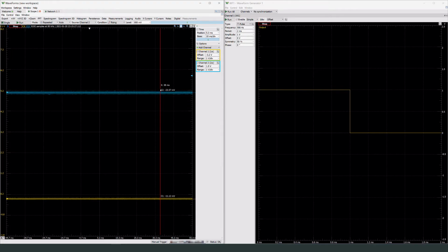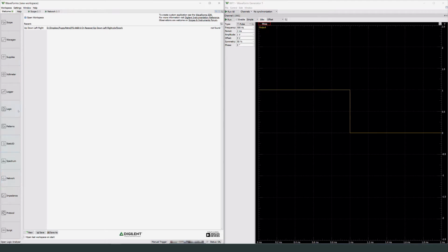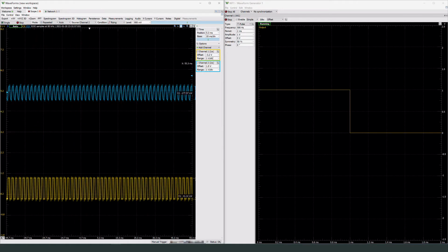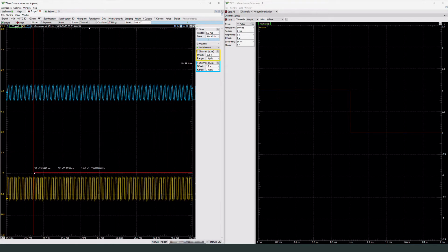But anything that we're dealing with right here, this is just great because it's got an entire electronics lab in one, where we have all these tools that we can use. And so right now we're going to use the oscilloscope and the waveform generator that we have plugged up. The waveform generator is plugged into the input of our circuit, and these are plugged in to measure the input on the yellow line here and the output on the blue line here. So if we start that and hit the trigger set, we'll be able to see the inputs and outputs. So we're inputting this square wave and we're outputting this sine wave right here.